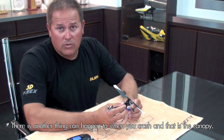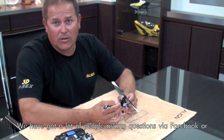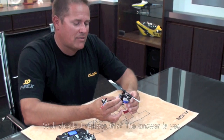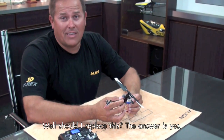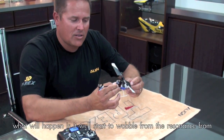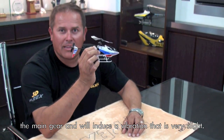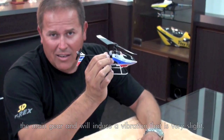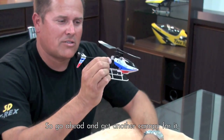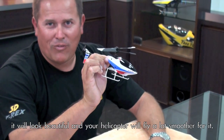There's another thing that can happen too when you crash, and that is the canopy. We've gotten some questions from a lot of people online via Facebook or our online website, and that is, they've cracked their canopy and they ask us basically, well, should I replace it? And the answer is yes. The reason you want to replace it is because if it's torn or cracked, what will happen is it'll start wobbling, with some of the resonance within the main gear here, and it'll induce a vibration. Very slight, but what that'll do is degrade the performance of the tail rotor system, and so you're going to want to make sure that you just go ahead and get another canopy for it. It'll look beautiful, and your helicopter will fly a lot smoother for it.